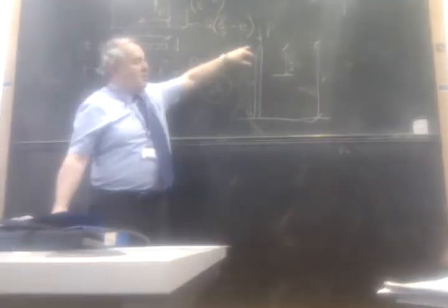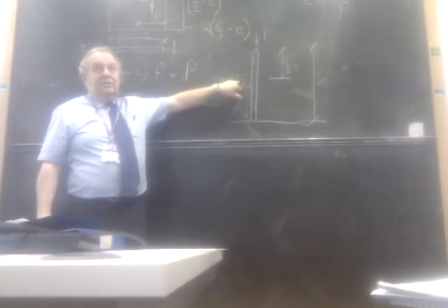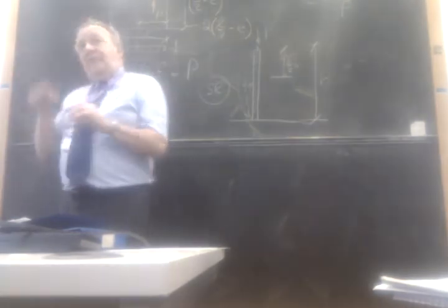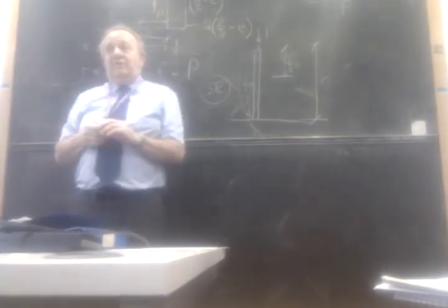it's a different problem. I don't know whether you can see it there, but that's EK, phi M, and U. There, how you deal with out-of-plane effects in walls. We wouldn't expect you to know those formulae. We'd give you those if you need them. But you would need to use these now to check this wall at mid-height. Here we've got eccentricities in there, capacity reduction factor, and there we've got a modifier U which sits in there. We'll give you those, so as long as you're familiar with them, the detail probably doesn't matter so much.